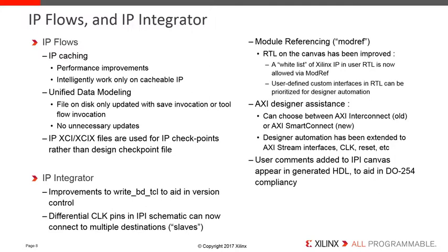IP Integrator now makes it even easier to leverage board awareness. From the IP Integrator canvas, board-aware input clocks can now connect from a single source to multiple destinations. Improvements have also been made to the module referencing flow, which enables users to take RTL and use it on the IPI canvas without going through the packager. The module referencing has been extended to support key Xilinx IP that customers might be using, such as block memory, debug cores, DSP48, and key math functions.